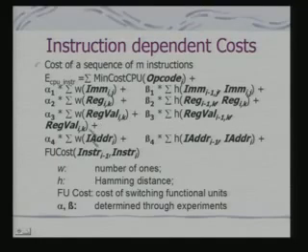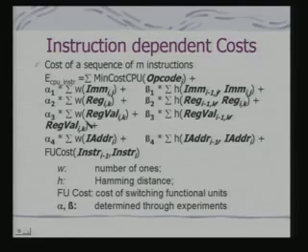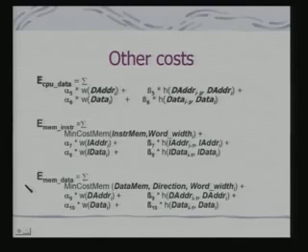In fact, these terms are modeling the activity which would take place on the bus for execution of an instruction, because execution of an instruction cannot take place without reference to operands. Operands can be immediate operands, operands can be register operands, there can be addresses for load store operations. So these terms should come in the energy model. And these alpha and beta are nothing but experimentally determined constants. There are similarly other terms to come in.